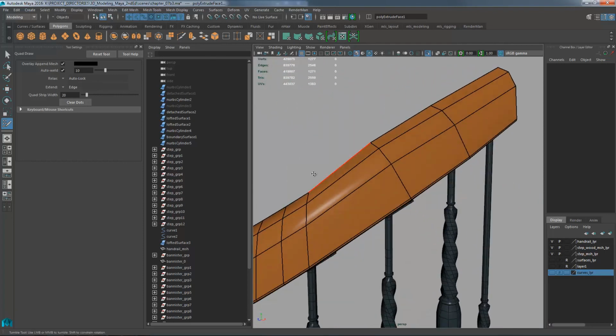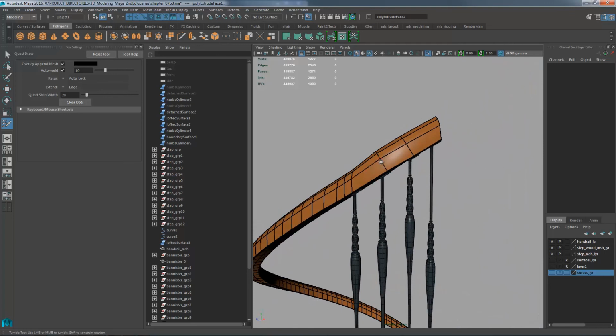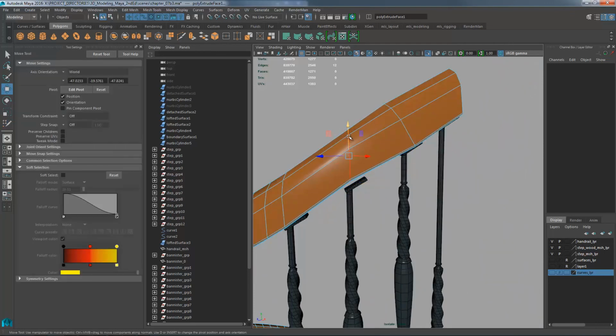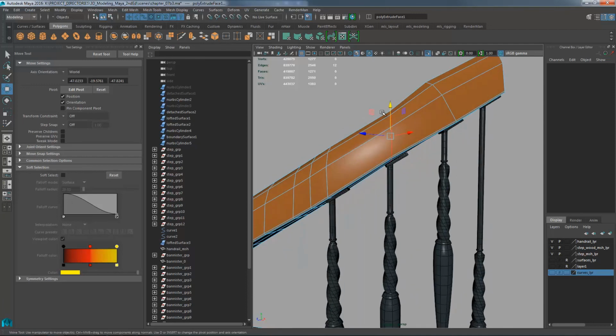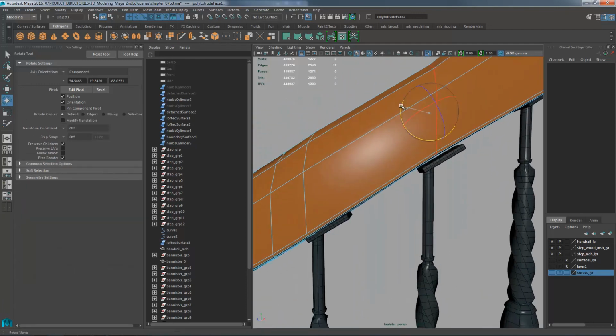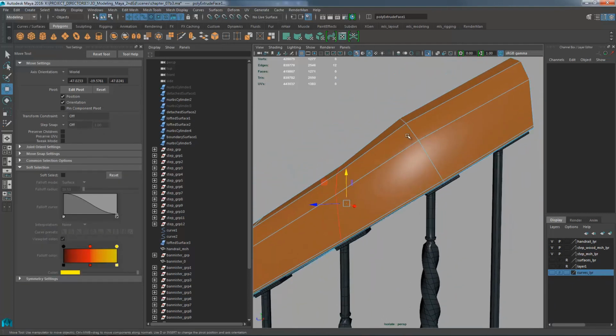Get it a good feel here, then use the multi-cut, probably without edge flow, to add in the remaining sections. Yeah, so just lean that edge forward, which will change the volume of it, and then push it down. And now that seems to be more correct, more like the volume that the handrail has.